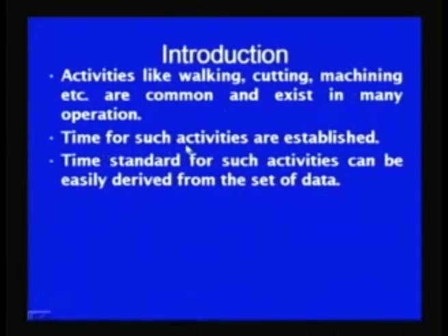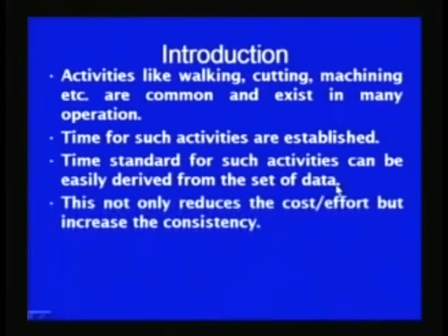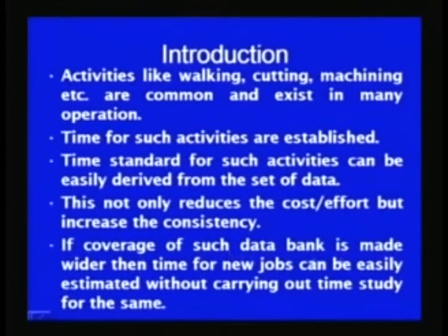So, time for such activities is established through time study, and the time standard for such activities can be easily derived from the set data. This not only reduces the cost and effort, but also increases the consistency. If the coverage of such a data bank is made wider, then the time for a new job can be easily estimated without carrying out the time study for the same. But initially the data bank is generated by the time study only.